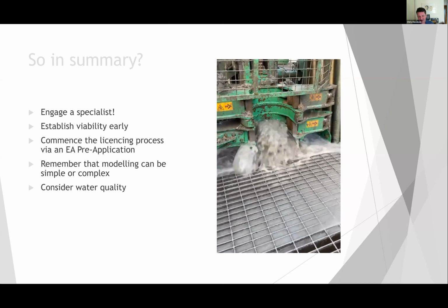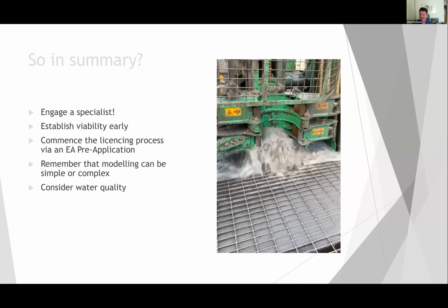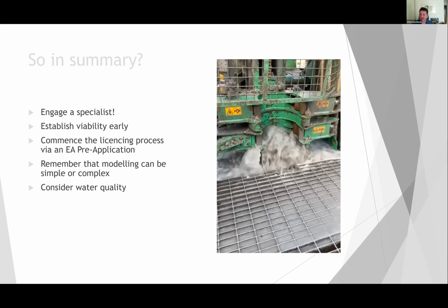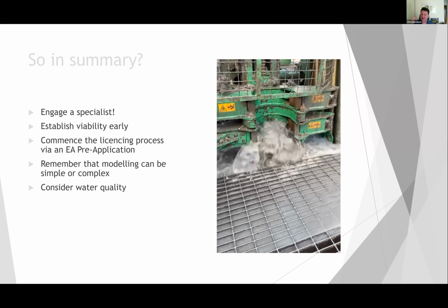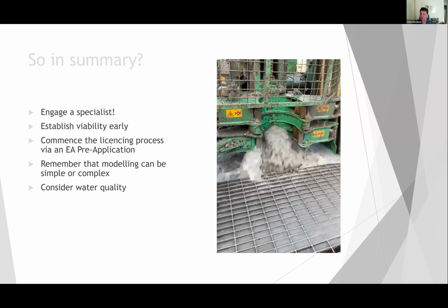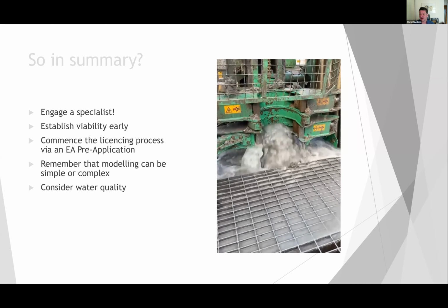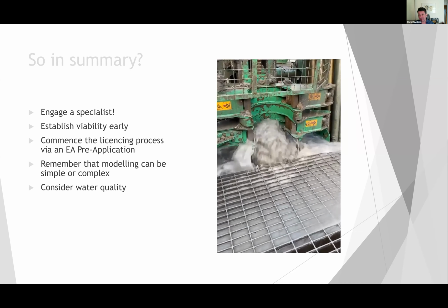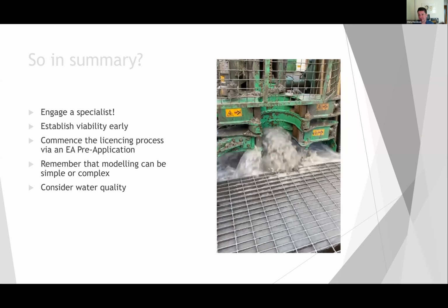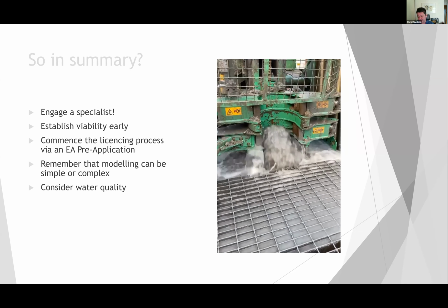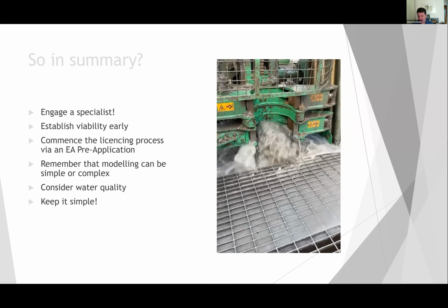Water quality is a key consideration. It's very important to design your system from day one to deal with the water quality that you're expecting from that location. And also it's important to revise the specification of things like the well pumps, the heat exchangers and so on, once you've got a concrete analysis of that water quality. And water quality, as I say, can shut a system down. It needs to be considered as a very important part of the system design. Keep it simple, as I say, particularly with controls.